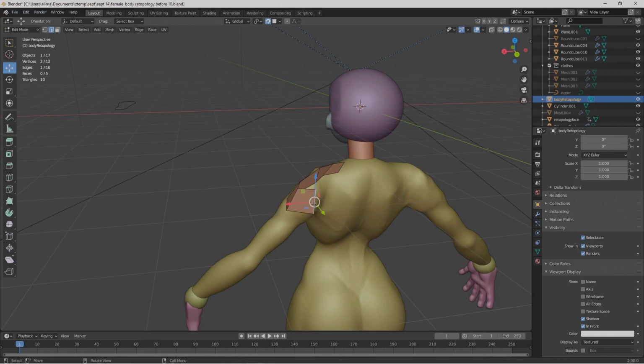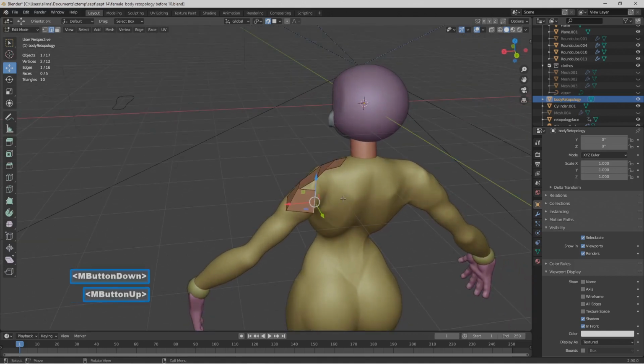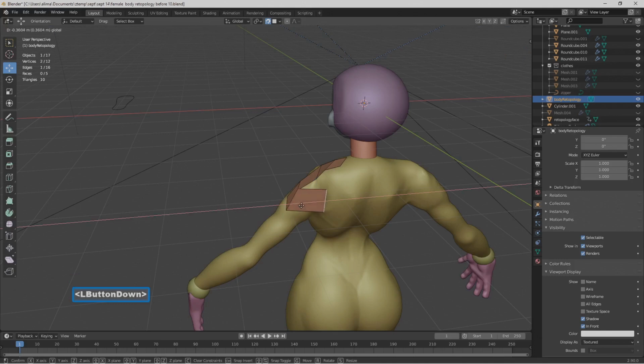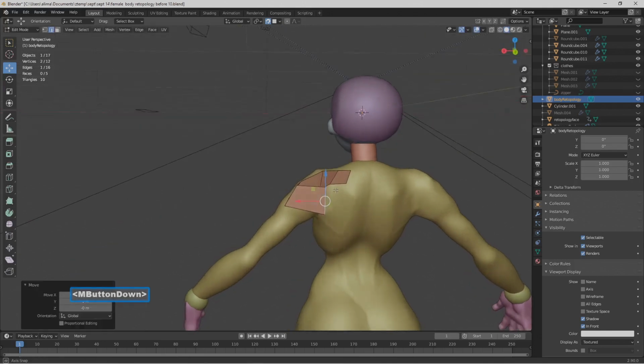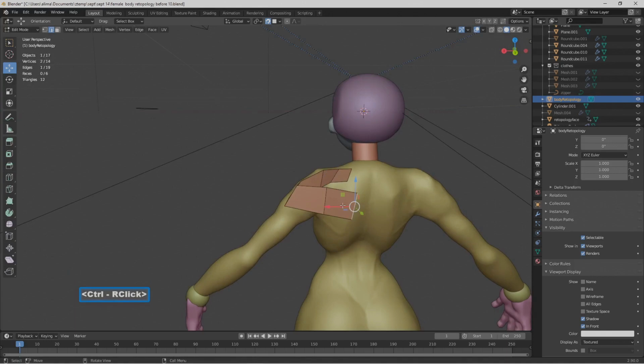So now we need 1 more piece that's going to go all the way to the back. I'm angling the view so that this isn't in the way. I'm going to take the manipulator and push this over more. I'm going to hold the middle mouse button to rotate the view, keeping the angle so that this geometry isn't in the way. I'll hold control, then right click. Here's that back geometry here.